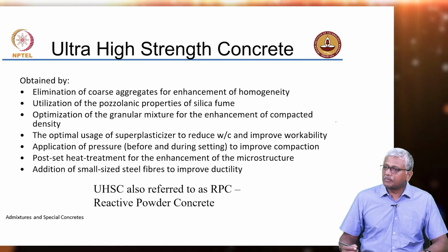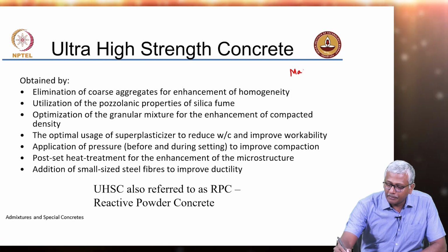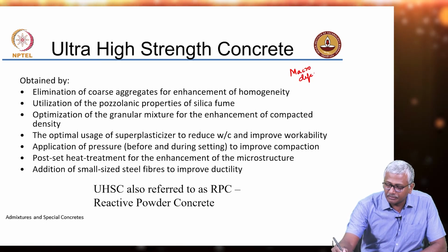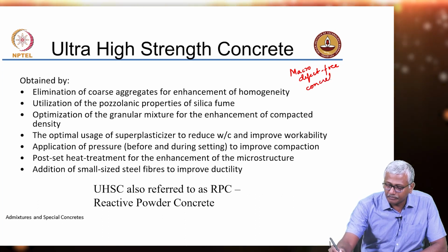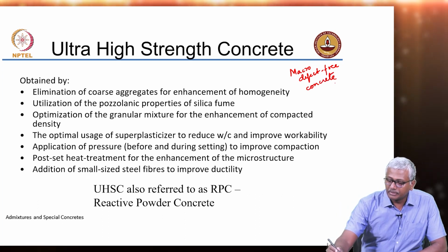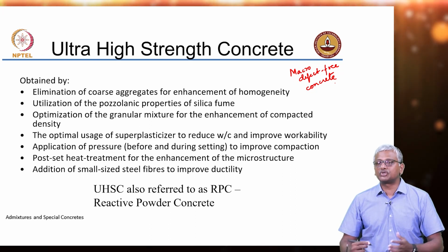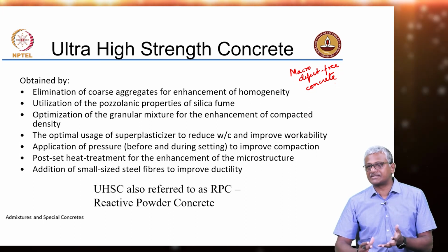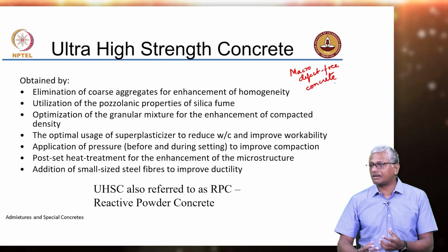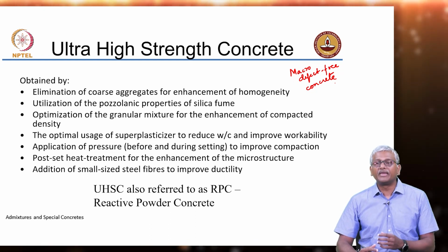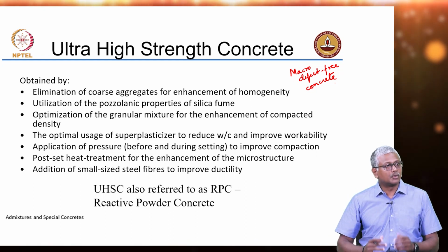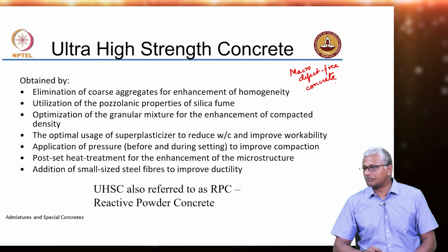In some papers, you may also have a reference to macro defect free concrete. That is a concrete in which you have done the processing in such a way that large defects like cracks and voids inside the system have been completely closed because of the pre-setting compaction that you give to such concrete.